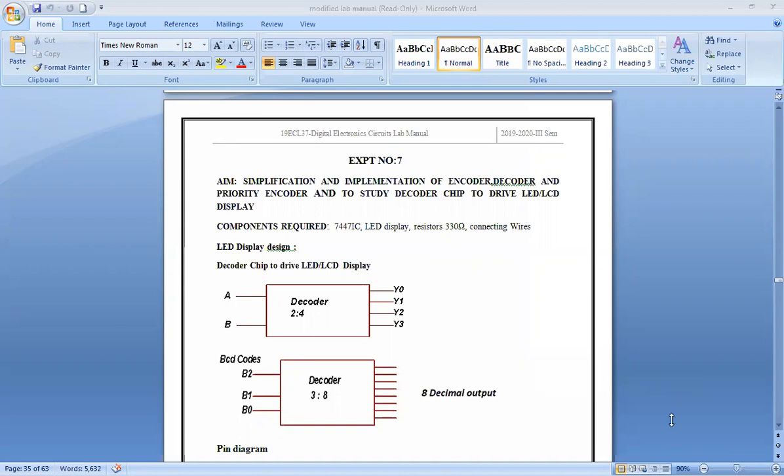How did we compare them? For example, if it's 4 bits, A3 to A0, B3 to B0, how did we compare them? For 4 bits, we will compare A3, B3. If it is greater, then it is greater. If it is lesser, it is lesser. If it is equal, we will go to A2, B2. Correct, so we will repeat this procedure bit by bit. Okay, Darshan, thank you.